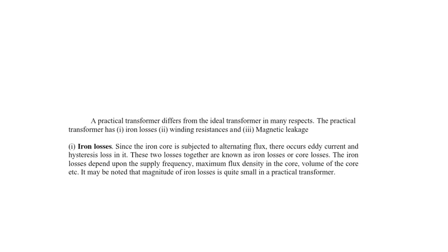The iron loss depends on the supply frequency, the maximum flux density in the core, the volume of the core, etc. It may be noted that the magnitude of iron losses is quite small in a practical transformer.